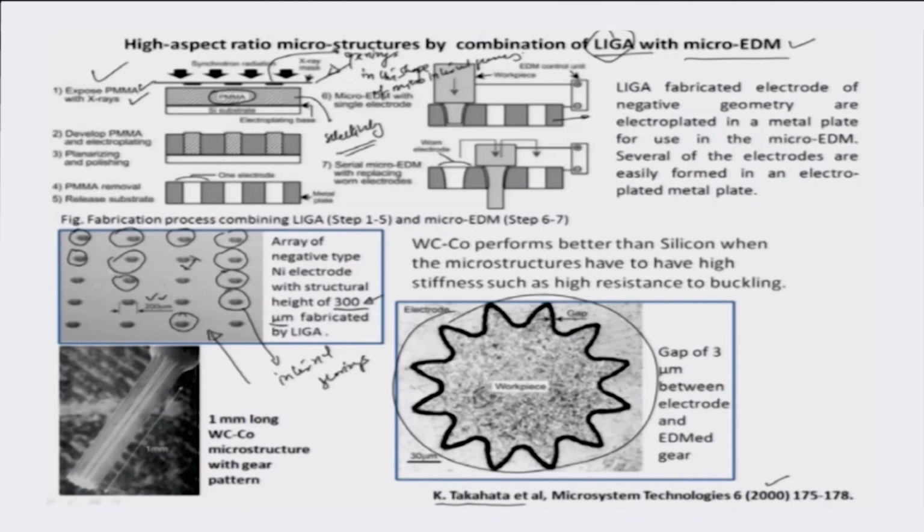Now, the PMMA is changed as soon as it gets exposed. If you expose this region, which you can see converted as this hatched area, the structure and properties of the PMMA here have changed, and you can develop the exposed PMMA out very well using a development solution.